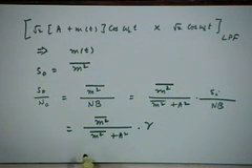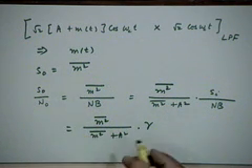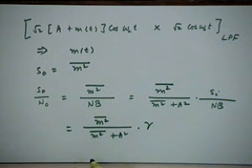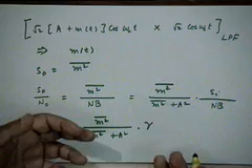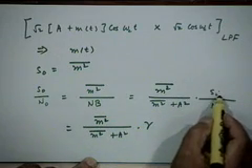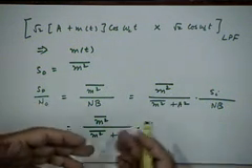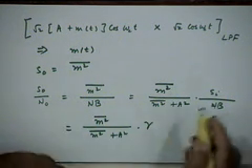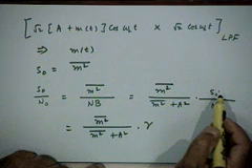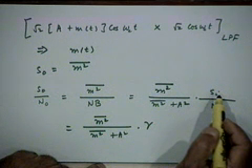So what do you find? That the output SNR is now smaller, and that is expected because when you are transmitting an AM signal with carrier, not the entire input power is useful in terms of the message, right? Part of this input power is carrier and part of this input power is message, right?